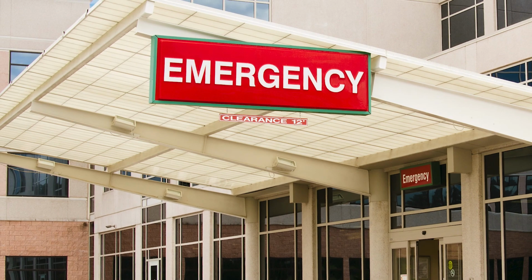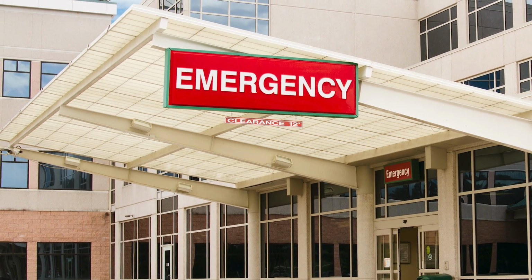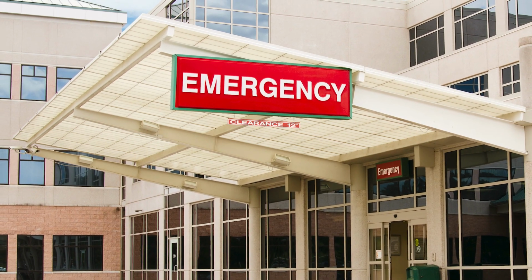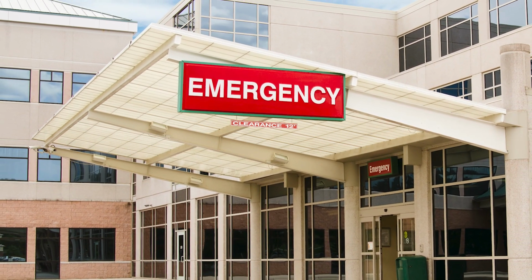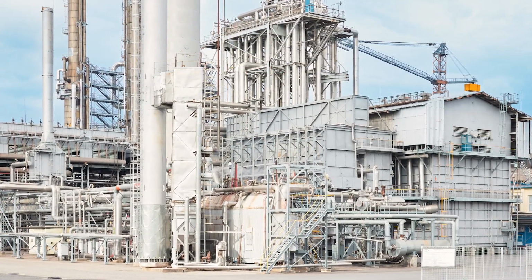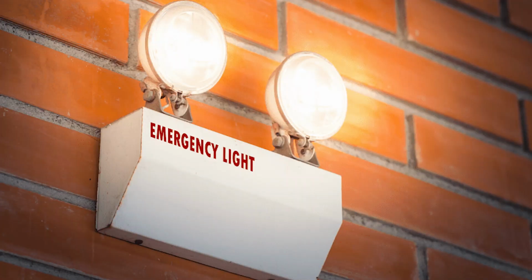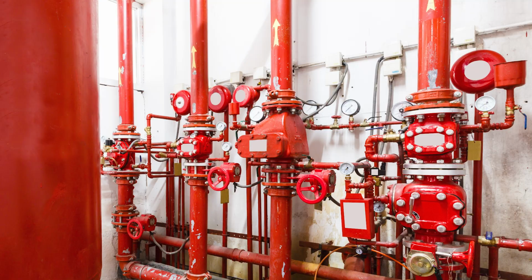If you have a hospital, hospitals are going to have requirements for selective coordination, which is in essence perfect coordination. So you have to have the coordination study that does that as well as the arc flash analysis. But then also in your commercial industrial facilities, you still have life safety systems, right? We have emergency lighting systems, we have fire pump systems in play, and those are also required to be selectively coordinated to some level. So yes, we have to have the coordination study and the arc flash study both from a perspective of code and standards.